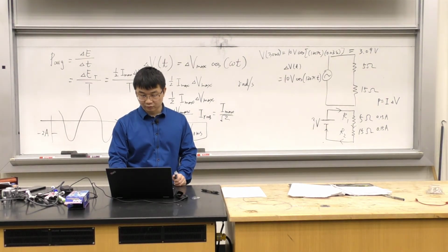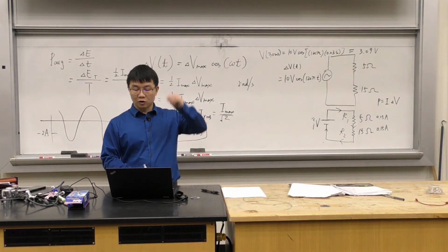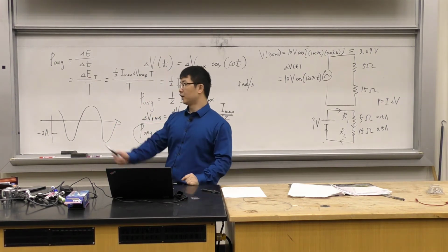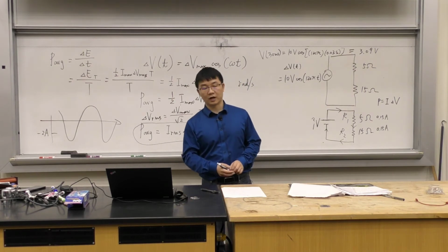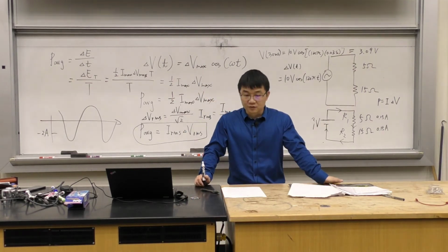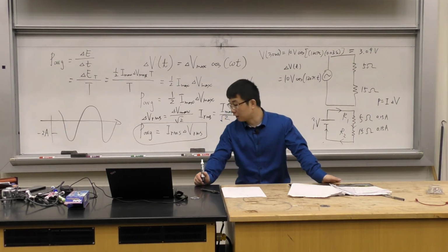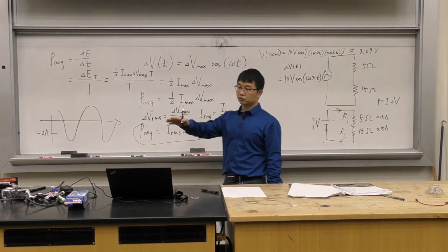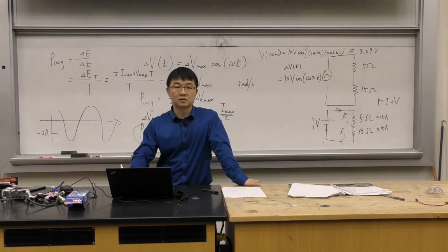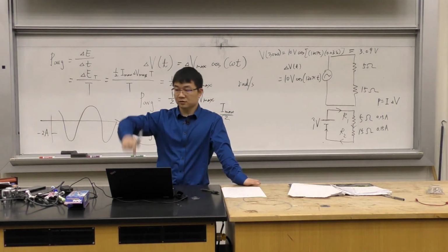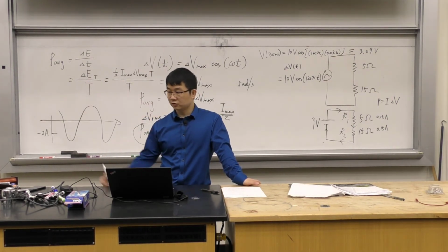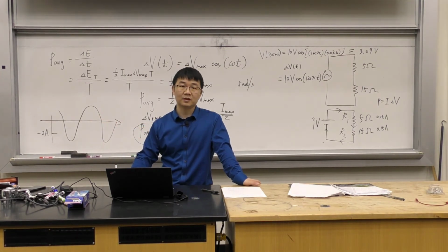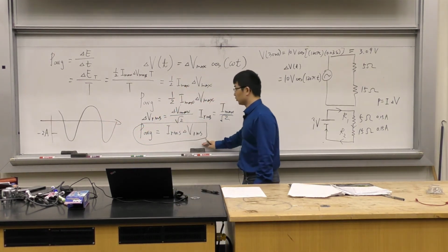Okay, and then when we talk about the voltage from this wall outlet, anyone knows the voltage you get from this wall outlet in this country? That's 120. But this 120 is the RMS value, okay, because the actual voltage you get from this wall outlet is changing, right? Because that's a function. Cosine function is changing all the time, right? So if you tell me the voltage you get from this wall outlet is 120, what does that mean? It's the RMS value, okay?